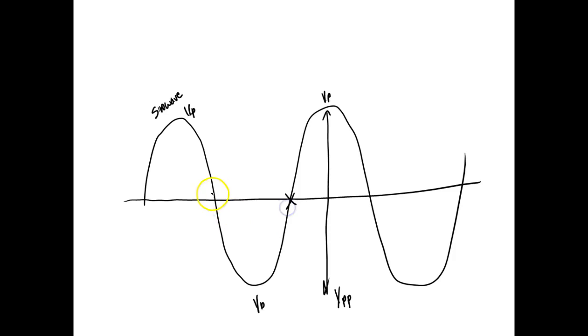So we come over here and notice I get no work during this time. We have no volts. If we have no volts, we have no current. If we have no current, we get no power, right? Understand? And then it comes up, not quite vertical, and then it lays over, and it hits V peak, and it's at V peak for no time. And as soon as it hits V peak, what happens? Yeah, it starts dropping down, right? Then it hits zero. So the work we get out of this is an average value. So my meter might measure 120 volts AC, but it takes about 370 volts to get 120 volts worth of work.